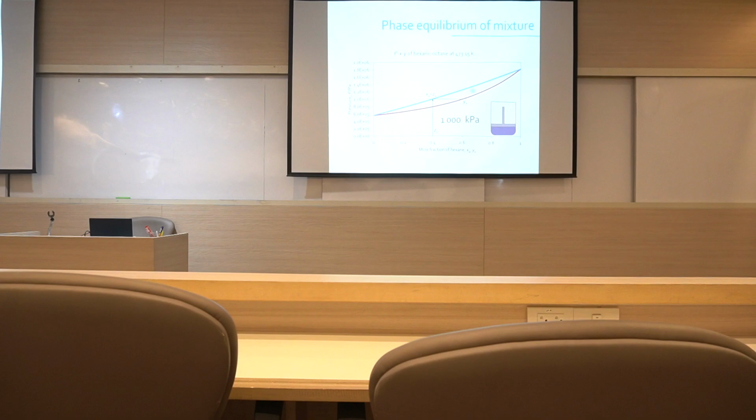And then we also have Y1. Y1 is, let's say, the theoretical composition of the vapor phase, which doesn't exist yet in this example. Okay? Or maybe you can think of Y1 as the composition of the first bubble that would appear if you lower the pressure very, very slightly. Okay, so that's bubble point. If your system is exactly at the bubble point, your system is entirely liquid. But if you lower the pressure only very slightly, the first bubble appears. The composition of the first bubble will be, at that point, Y1.